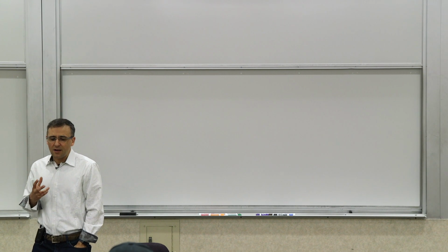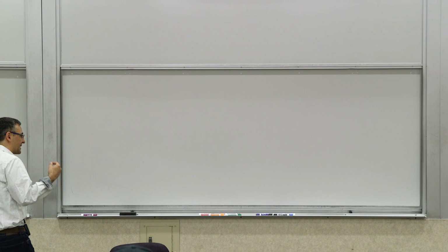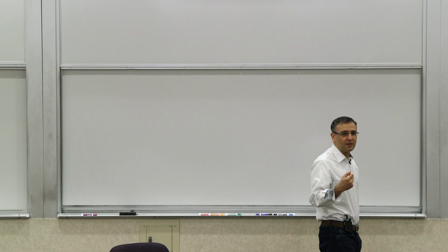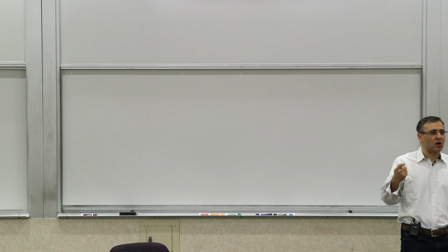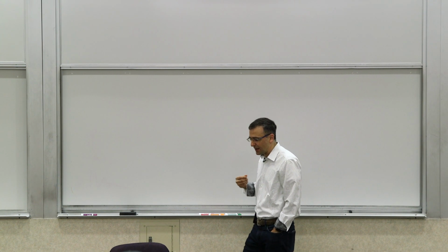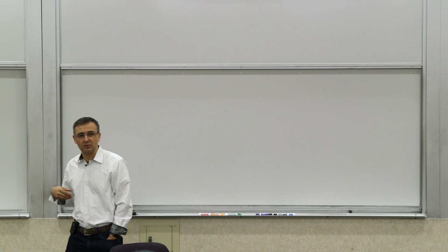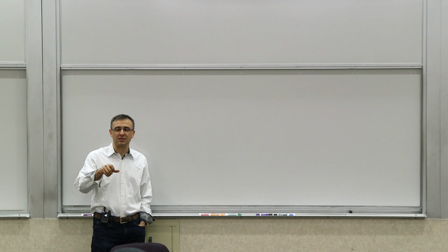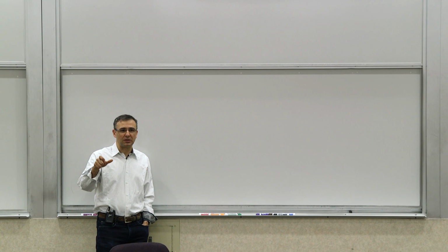All right, last few lectures we really looked at stability criteria. We started with an example of a 3-stage amplifier, a simple amplifier, and we saw that it was actually unstable when we applied a sufficient amount of feedback to it. As we applied feedback initially, it was stable. As we increased the amount of feedback we applied, it became unstable.